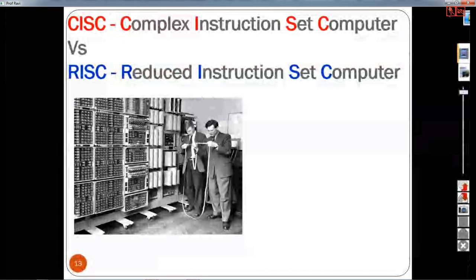Now if you look at some of the low-end devices of PIC, they are 12C5X, 16C5X, and 16C505. Coming to the mid-range PIC architectures, they are built by upgrading low-end architectures with more peripherals, more registers, and more data and program memory.